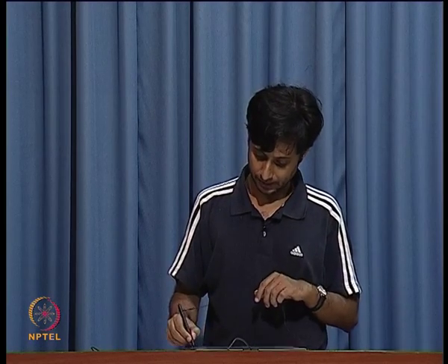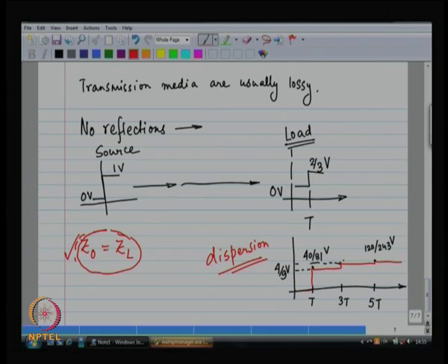That is going to further minimize reflections from the source side. So, that is the second tier of what you can do. First we would like to have Z L equal to Z naught, then we would also like Z s to be equal to Z naught. This is also something good, not the most important, the second most important.